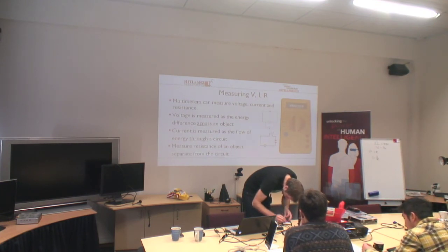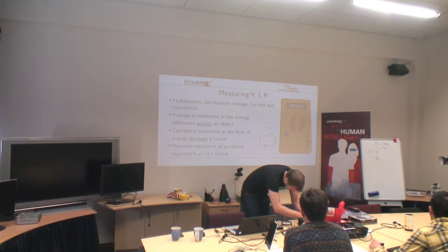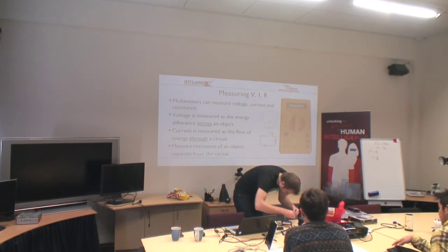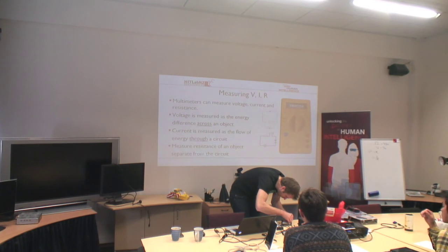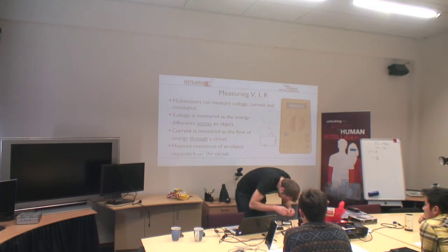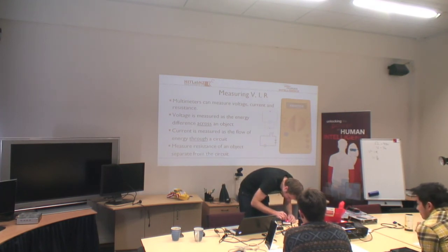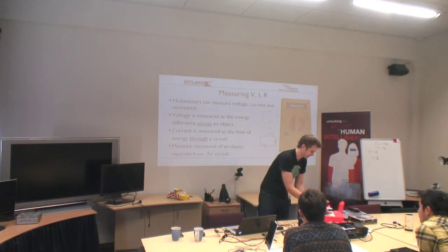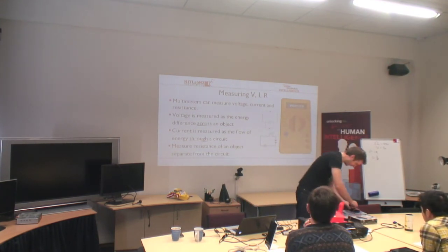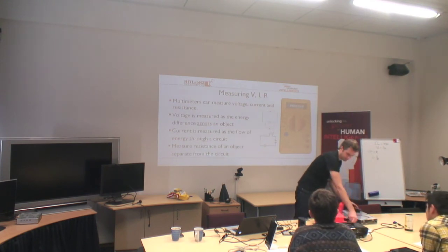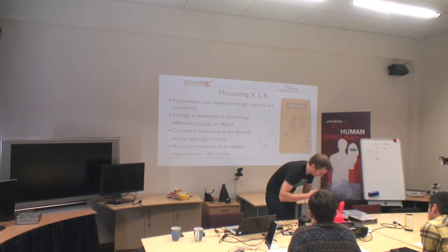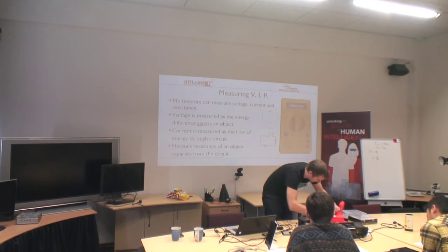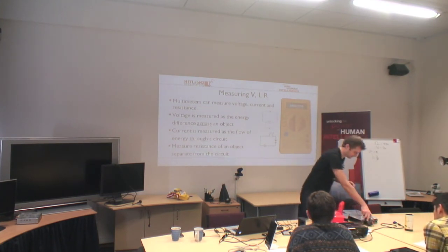That up to there and around, and then hook this one up to 5 volts. Right, so say I want to measure the voltage across this LED. I will flick it round to volts, and I will put one end on one leg of the LED, the other on, prop this up so you guys can see.